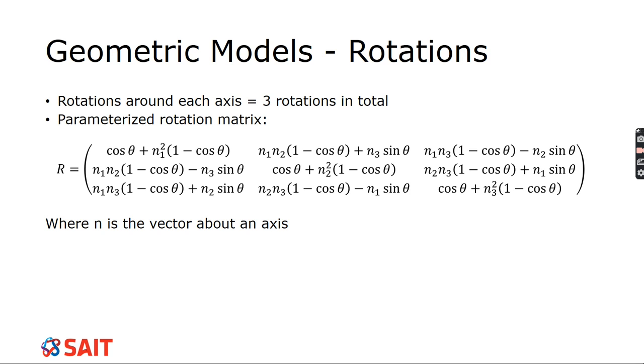Every single system that we have in Airborne Lidar: the GPS, the IMU, the laser scanner itself, the bore of the laser scanner, which is where the light actually shines through, the WGS84 coordinate system. We have local coordinate systems, which is how the light interacts with the target itself. So there's a ton of different coordinate systems that we're dealing with here, and we have to rotate them all to put them into a single coordinate system. There's translations as well.